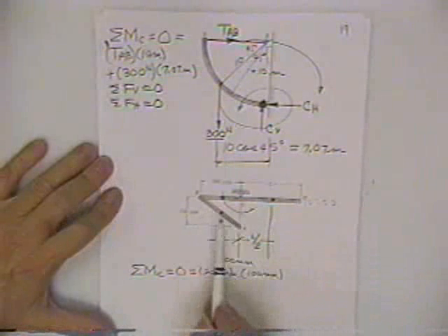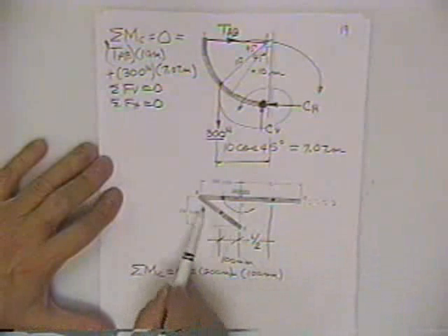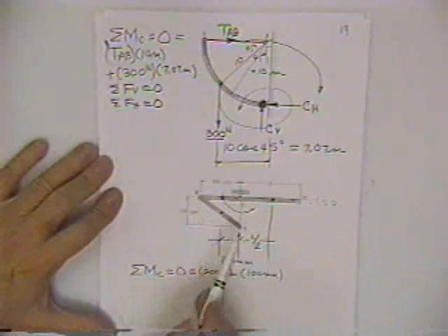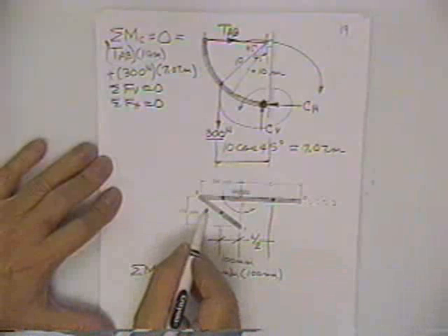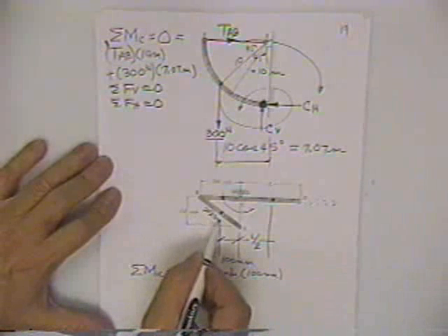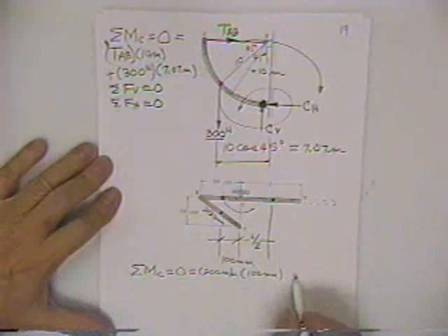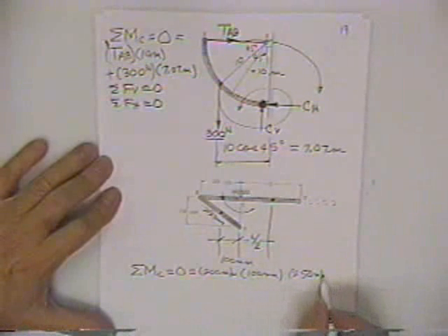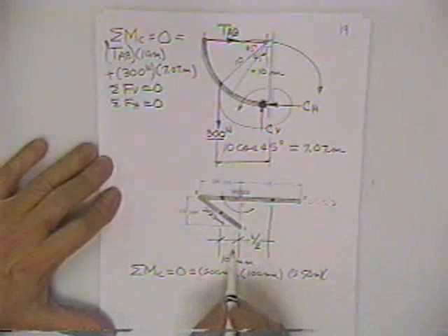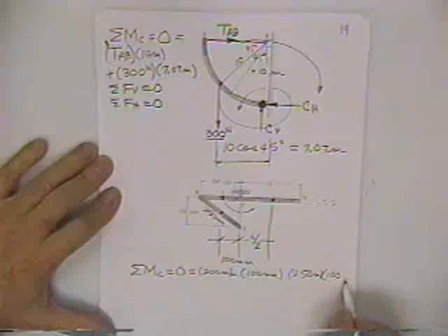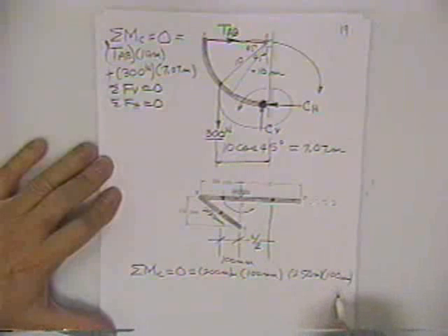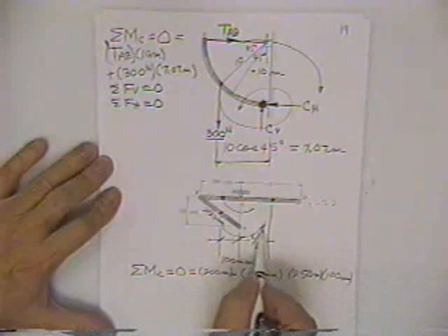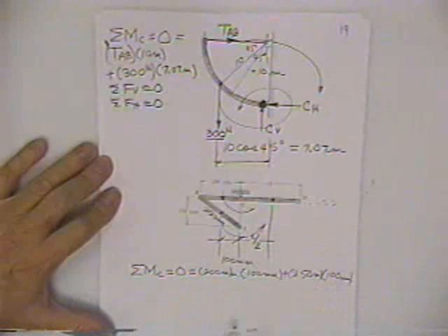Next, I got to know how long that little stick there is. It's 200 squared plus 150 squared. Take a square root. 250. It's a 250 long stick. So then I would have a 250 millimeter long stick multiplied times, he has the same 100 length. And were he to get away from it, he also would pull the bar that way. That's a plus tendency.